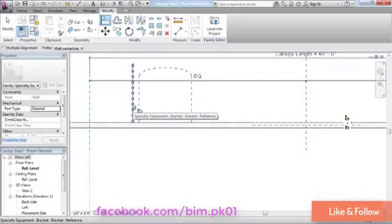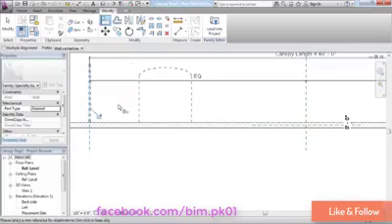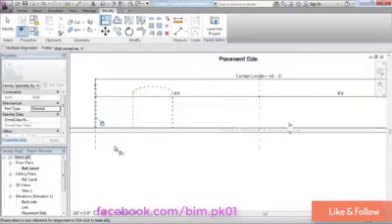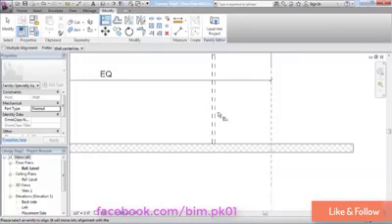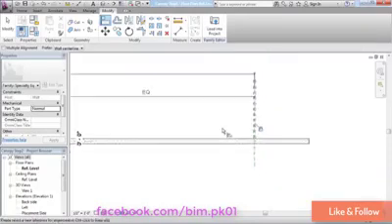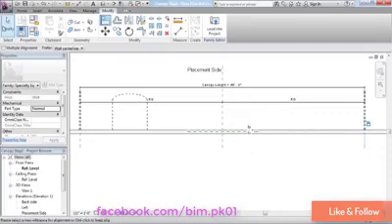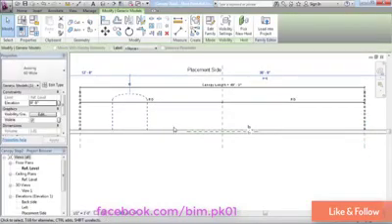That's actually what I want to use as the point to align to. And that will line up the bracket directly on the center of this left edge reference plane, and I'm going to lock that. And I'll come over here and repeat the step on this side, again aligning to the center, and I'll lock that. And then let's repeat the whole thing with this awning.